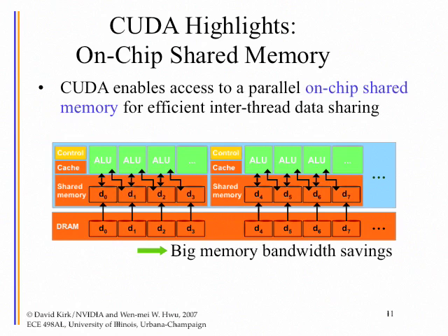The bandwidth out of the DRAM is actually pins. We're talking about GPU pins, and those pins are expensive. A typical high-end chip that goes out today has about 86.4 gigabytes per second, and the next generation will be right around 100 gigabytes per second going between the GPU and the DRAM.